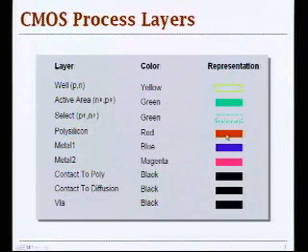And then you have another terminal for your transistor that is polysilicon, that sits on top, that defines your gate of your device. And then from there, you have interconnect infrastructure. You have a number of metal layers in different processes, more and more as technologies advance, and those serve to connect your devices into a circuit that you designed. So you have metal 1 that connects to your source and drain regions, and then you have higher metal layers that you need to escape over to be able to connect more complicated structures.